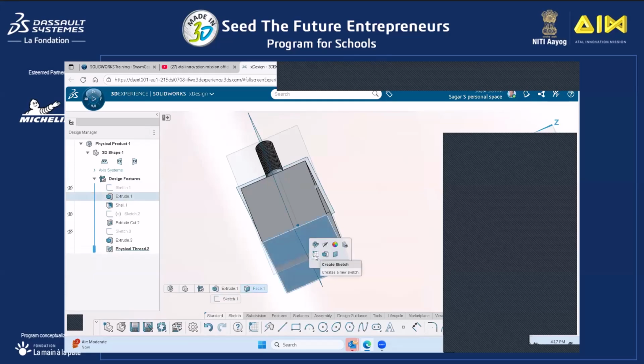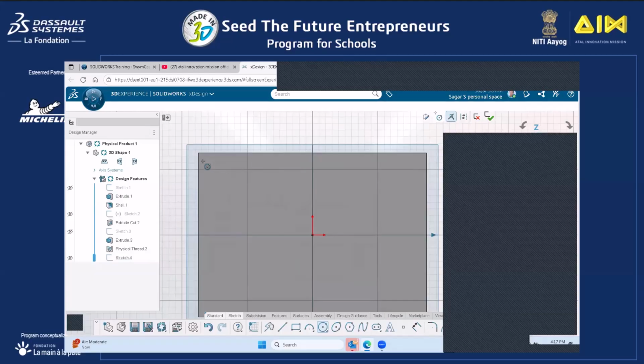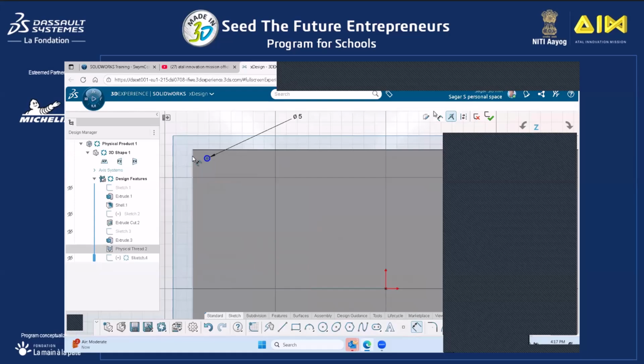I'm going to create a fine mesh here. So I will create a sketch here. Let us create a sketch of fine mesh. For example, I have created one circle here. I will provide some dimensions to it. You want fine mesh, so I will make it of very small size. Let us say 5 millimeters. And I will position it this way 5 mm, this way 5 mm.